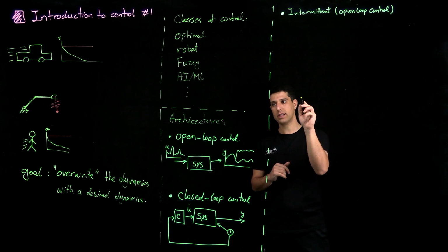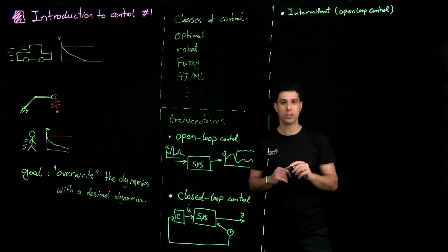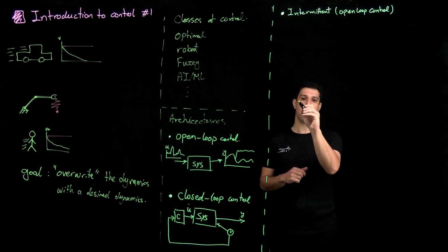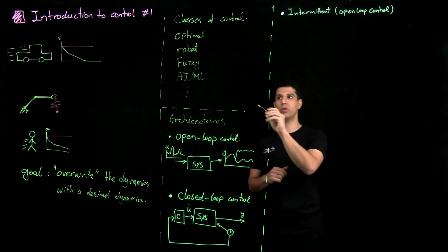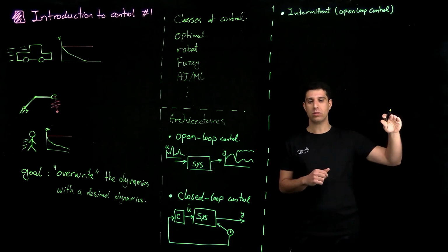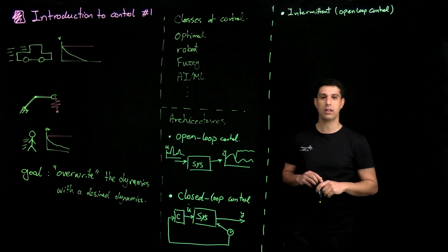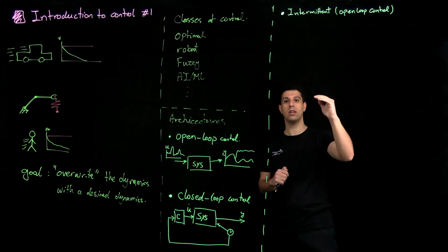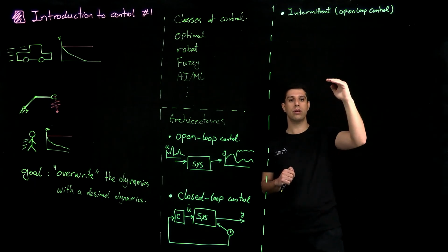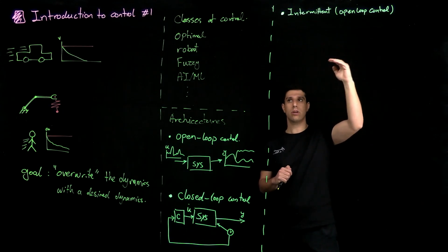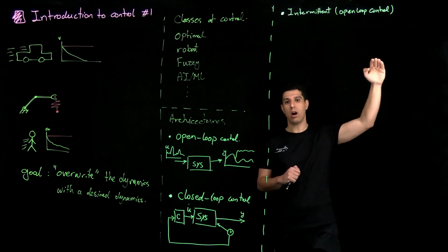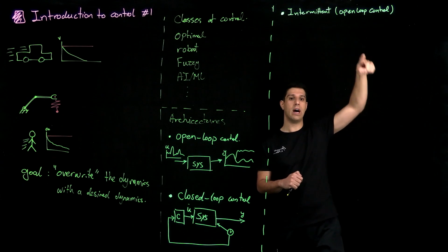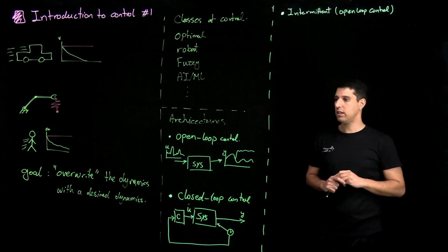So you define a set point temperature for the house. As in winter, the inside temperature drops, the system waits until it reaches a certain lower bound and then turns on the heater. So it goes from 0 to 100% heating capacity. Then your temperature starts to increase, and you're monitoring it, and as it reaches a higher threshold, you say, okay, it's warm enough, and you turn off, and essentially this going up and down happens in the temperature of the house.